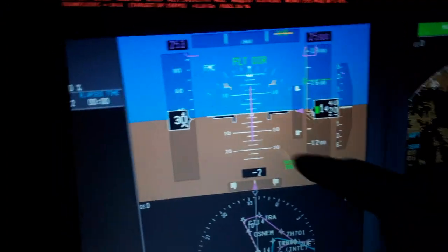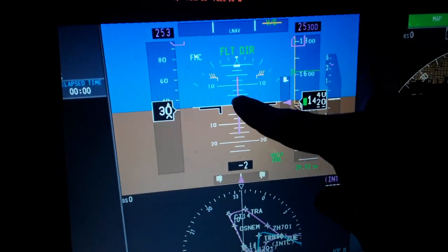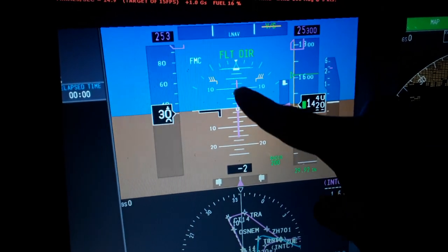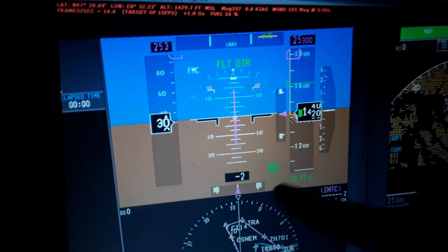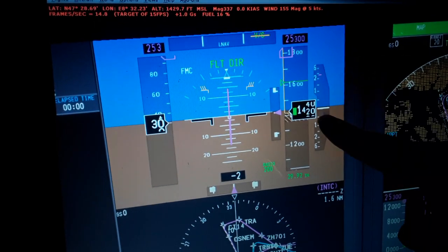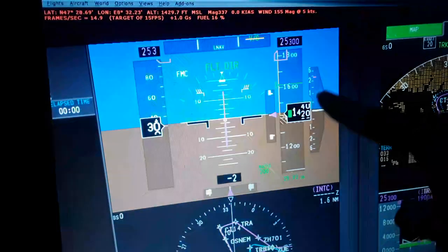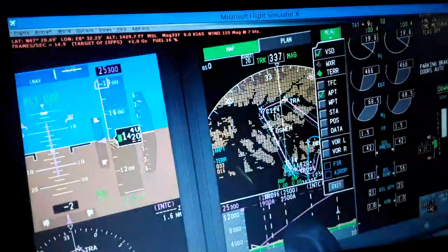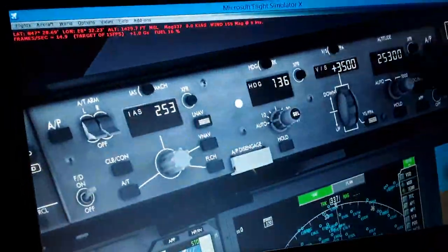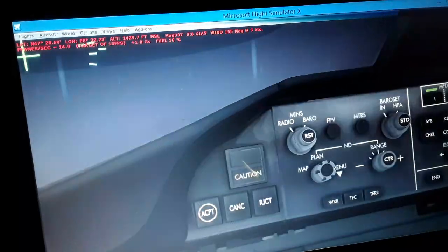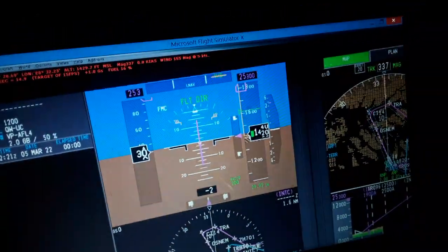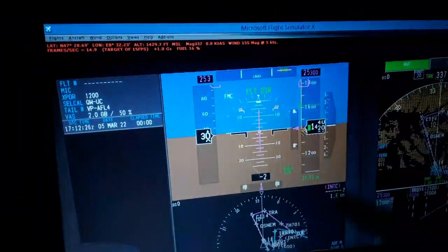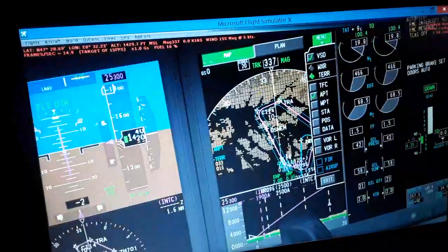You can see the display, the altitude indicator, pitch ladder in degrees, 2.5, 5, 7.5, 10 degrees, plus or minus this climb or descent. We have also the vertical rate of climb and descent of the aircraft, feet per minute. Or you can also use the steepness of the trigonometric angles. Over here, the flight path angle mode from the autopilot flight director system panel. So we have the radio altitude above ground level, the barometric pressure of the outside atmosphere, flight director, LNAV, VNAV.